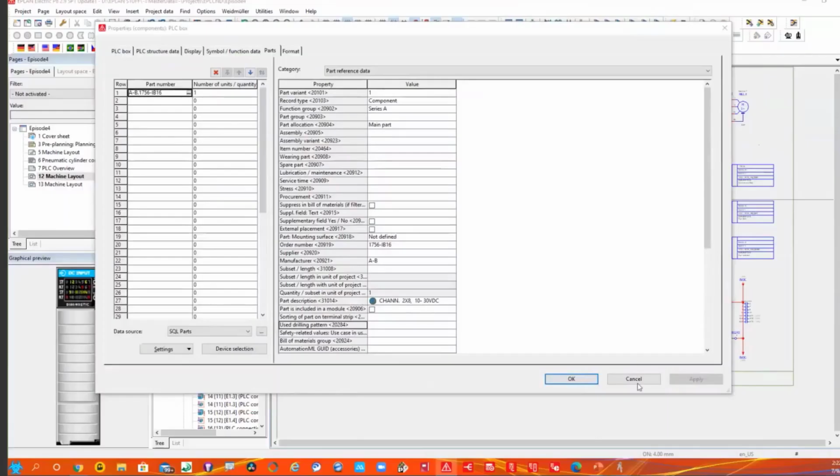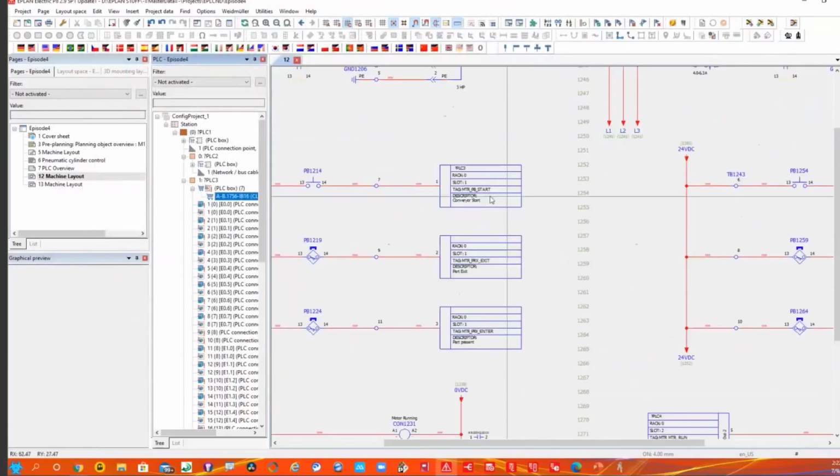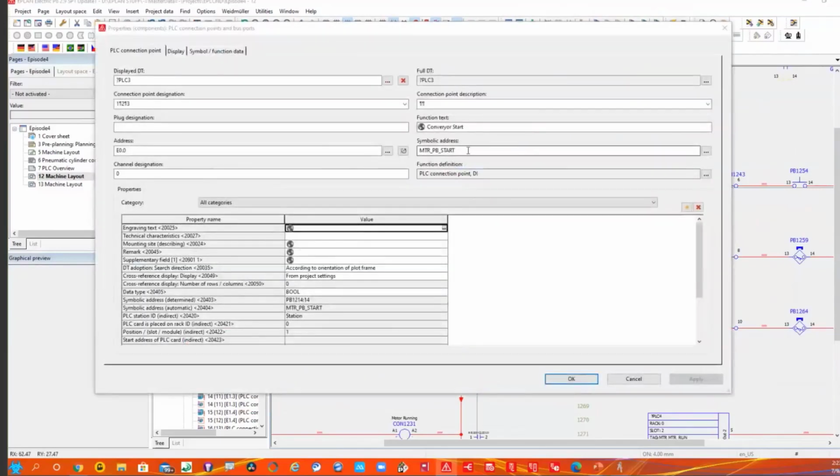Thank you, Sergio. So we have a couple more questions. What information do you have to put into the parts in EPLAN to be able to transfer information, such as function text to Studio 5000? Right. The function text is technically the information that you get from the IO point. Now, the function text property, or this basically would be the property, the description property, and the symbolic property.